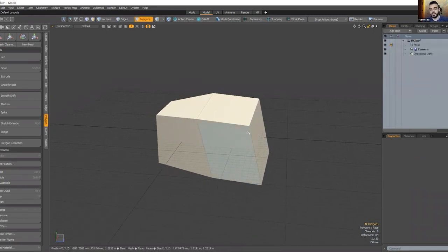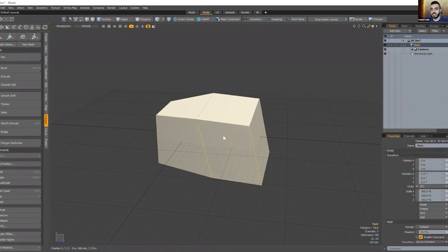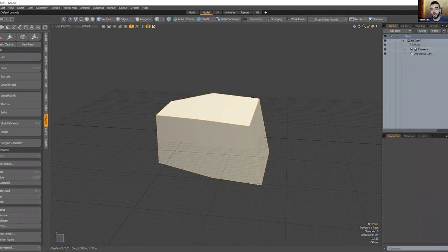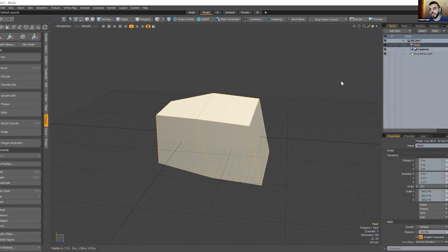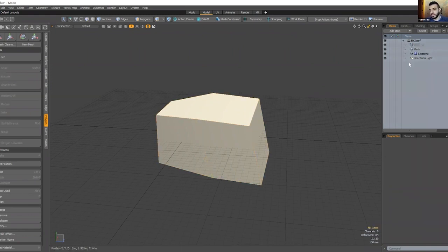when you are in primitive object mode, where you can select the whole object, you can see that this is the mesh that you're working with. You have the camera, you have a direct light. Of course, your layers are automatically added as soon as you add a mesh, or you can always add a new mesh that's empty, which is basically the equivalent of a new layer, by just pressing N on your keyboard. And that will give you a new set or a new layer for a new mesh.